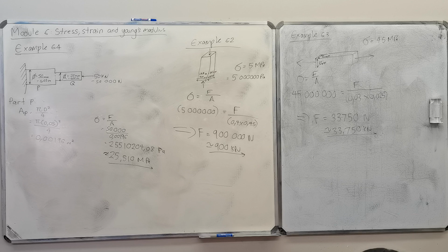You'll understand what I did there, guys? Not difficult. We just worked out the cross-sectional area of the cylinder and divided the force being applied by it. We got the stress in part P. Now, let's do it for part Q.